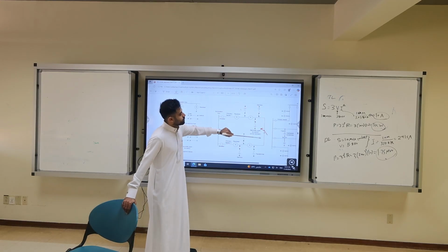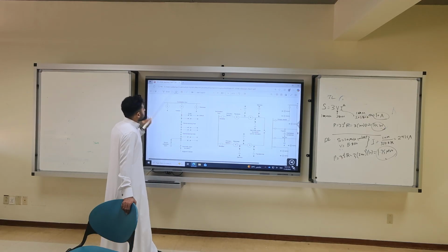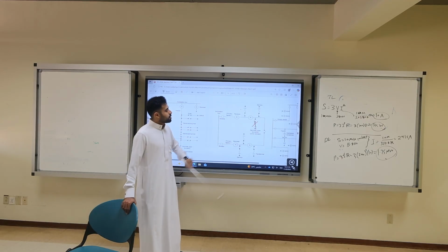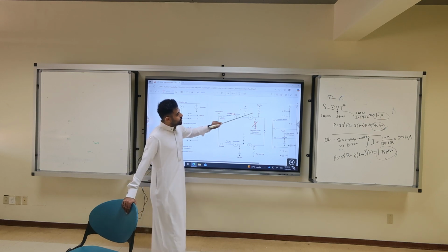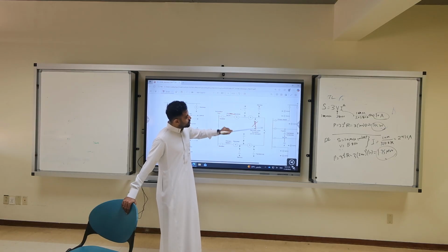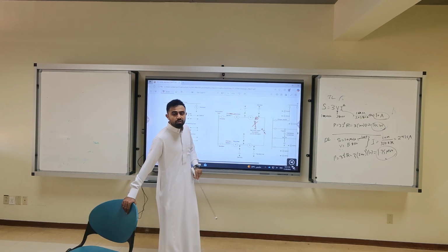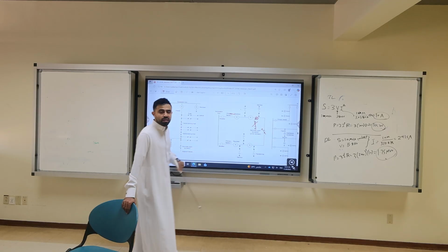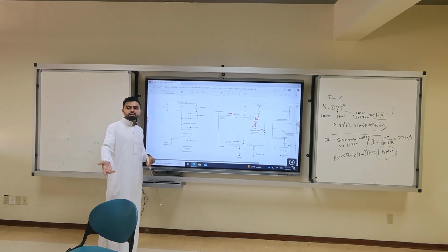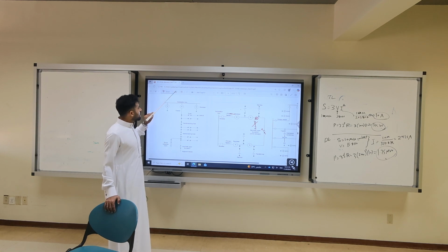Another scenario is what if we have an issue here? This recloser will open, still the electricity, this is on, this will be off. This tie breaker is on. Now, will it be off? No, because they are tied together. There is nothing here. If there were a recloser here, we can close this and allow the electricity to move here and isolate this. So it depends on the topology, how many reclosers we have, how many breakers we have, how many fuses.